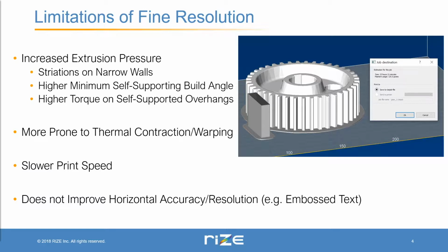Another factor that can affect that is the height of the walls. If your narrow walls are quite short, then it may not be an issue, but if you're building tall parts with narrow walls, then you're more likely to see that effect, especially near the top.